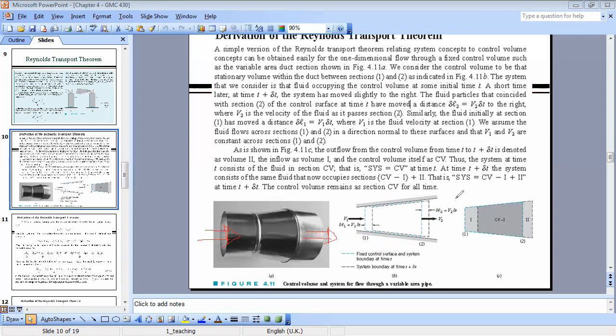So at a certain instant, I will consider a certain part of the particles, a certain system. The system of particles here is limited by the blue line. You see the blue line? So these are the particles I am tracking. You have two instants where you are exploring your system, instant 1 and instant 2. At instant 1, you just have this part of particles outside of the control volume, and the other part is inside the control volume.